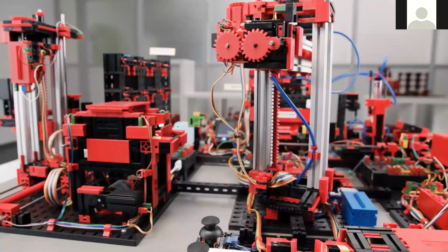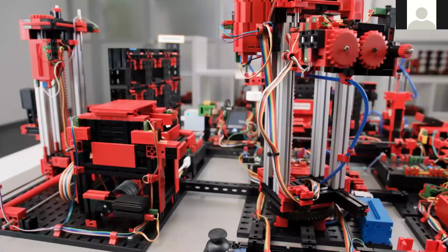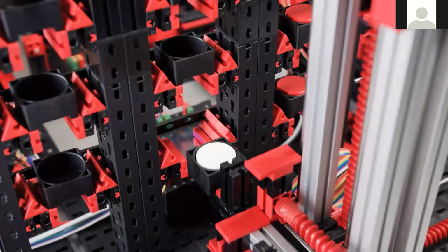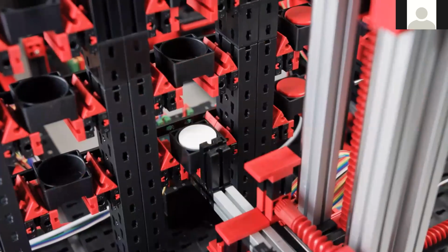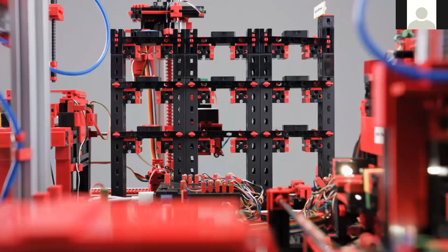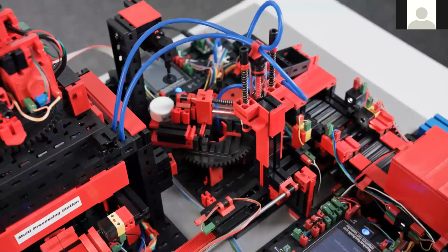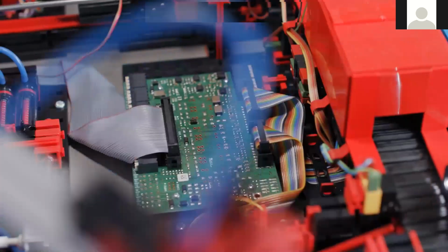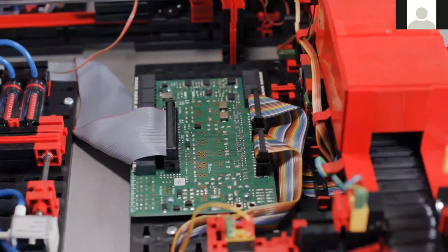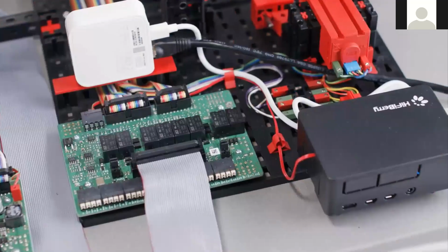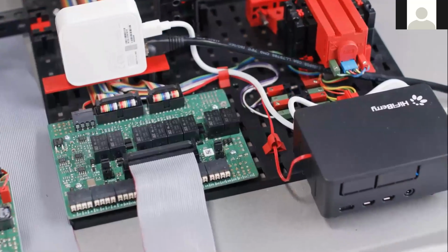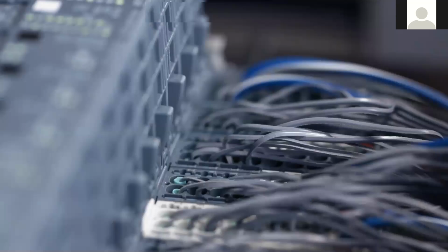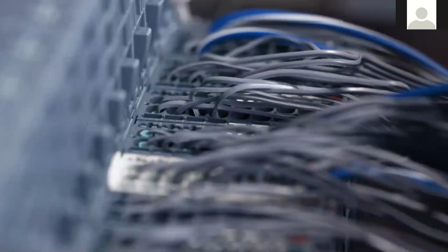The training and simulation model demonstrates the process from the delivery, collection, and storing of the materials through the ordering and the manufacturing processes to delivering the finished product. The training factory industry is controlled by a PLC controller, a Raspberry Pi as IoT gateway, and a TXT controller. The PLC program controls the individual modules of the factory. The program is written in structured text.